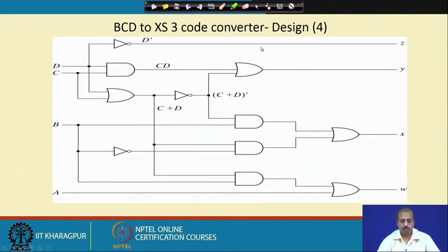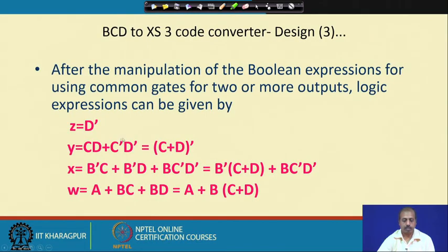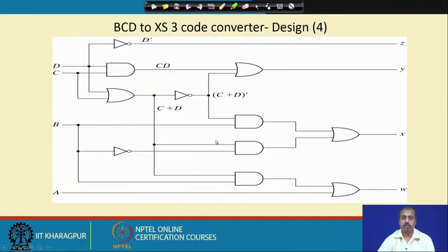So, this is the function for X, Y, Z and W. In fact, in this case the XNOR gate and NOR gate are becoming similar. So, we can use this for Y. Instead of doing XNOR, we can do NOR also. That will give us a similar result because of the presence of don't cares.